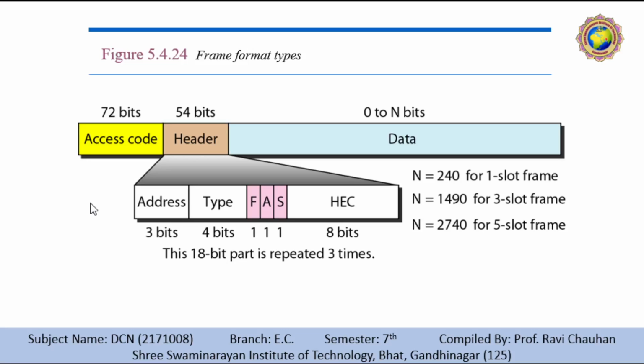A device that uses a 3 slot frame remains at the same hop for our entire 3 slots. Even though only 1 hop number is used, 3 hop numbers are consumed. That means the hop number for each frame is equal to the first slot of the frame.